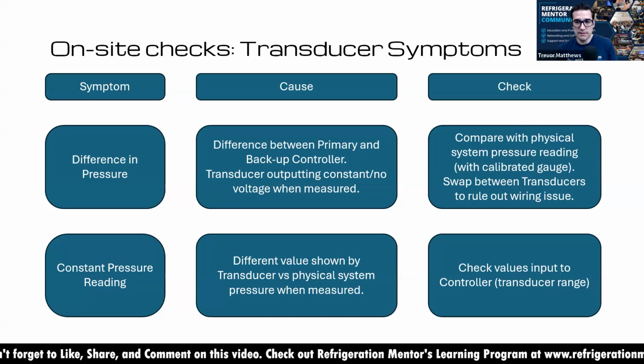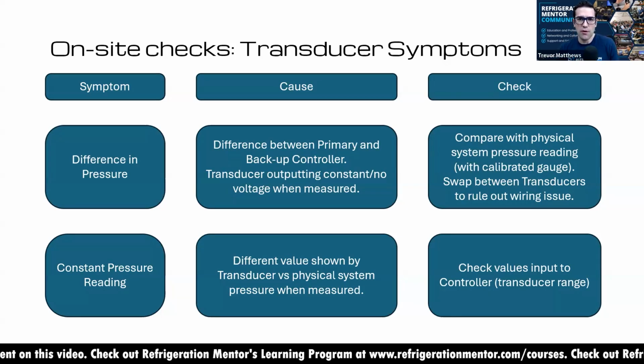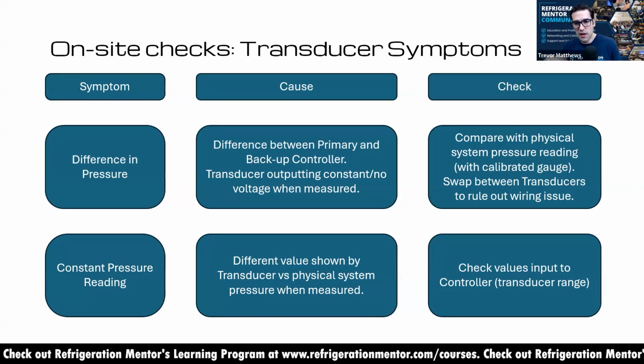And so what he did, he took his high pressure gauge, put it on the flash tank, and it said 580 psi, so around 40-ish bar. And he's like, what's going on? So he actually pulled off the transducer and it was full of oil. He just emptied it out of oil, put it back on, and it read correctly. So some things can be a little tricky like that.